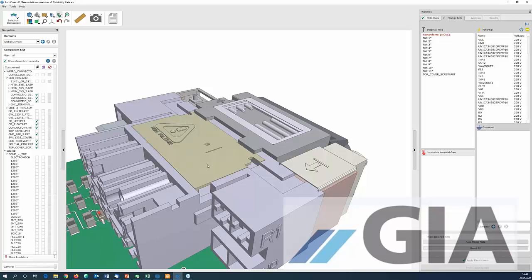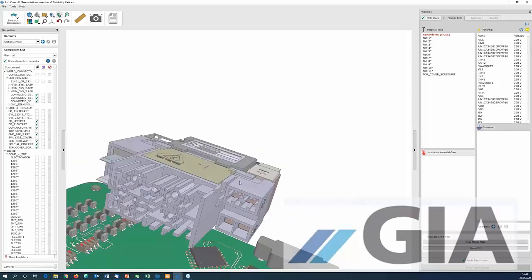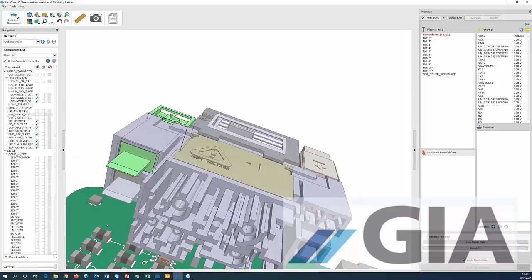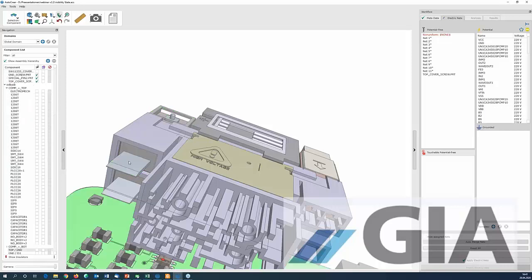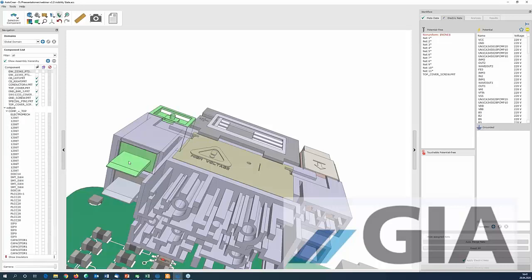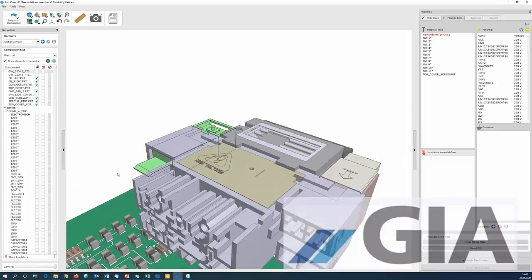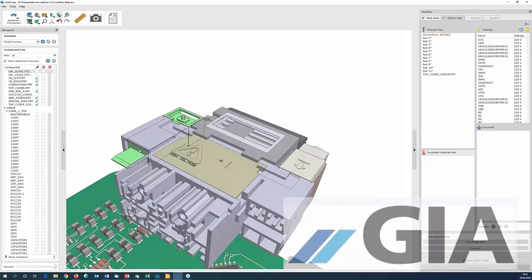It's not totally the opposite, because there might be some components, like for example this one here, or the entire PCB components, which are not of one homogeneous material, and we can do the hide and show operations only on solid bodies. So if there is a solid body with different materials, with insulators and with conductive, they will appear in both visibility states.